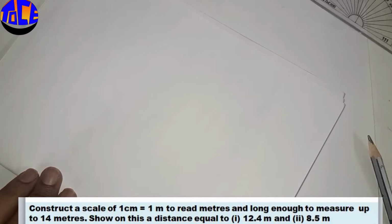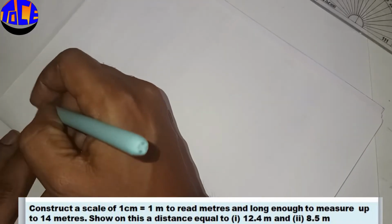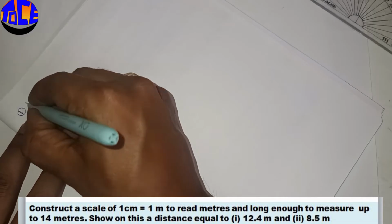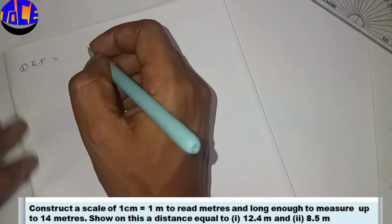So let us discuss one more topic from the engineering graphics. By understanding the question which is displayed on the screen, here we are going to consider the scale which is long enough to measure 14 meters, as given in the question. So before drawing the scale, we need to calculate a few things. The first one is the RF value, that is the representative fraction value.